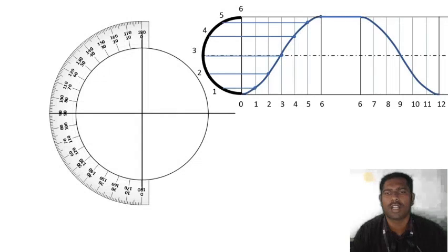Then we are going to draw the cam profile. For drawing the cam profile, we need the base circle radius. The question gives the base circle radius as 5 centimeter. So draw the cam circle radius as 5. Better we can split those into quadrants and mark the axis of the cam, because the axis of the cam carries the follower,